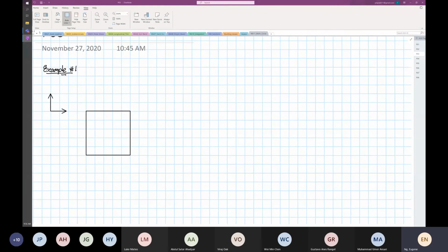So this is our x and this is our y. Over here we have a normal stress of 30 megapascal. You can see that that is in tension. Then we have another stress down here, which is 40 megapascal. And then we have a positive shear configuration, which is equal to 15 megapascal.